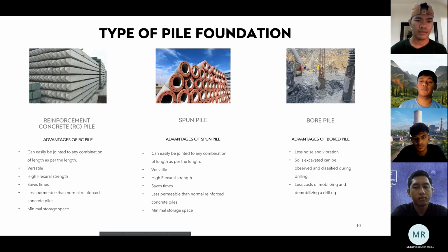So the third is the bored pile. The advantage of using this bored pile is less noise and vibration. Excavated soil can be observed and classified during the drilling.